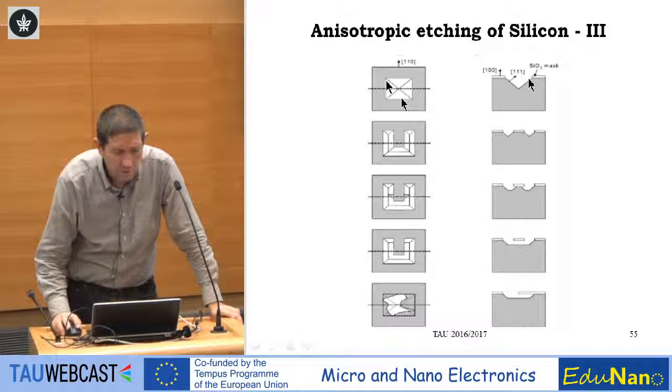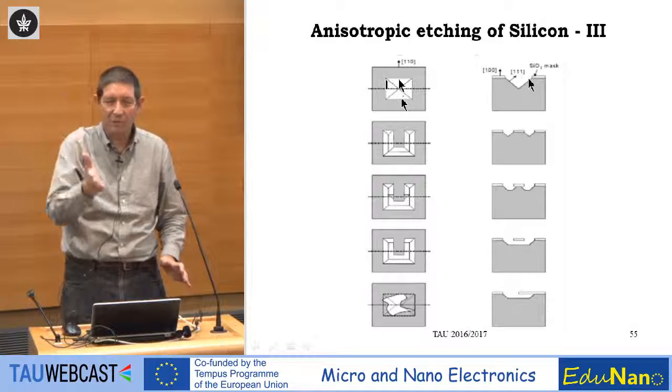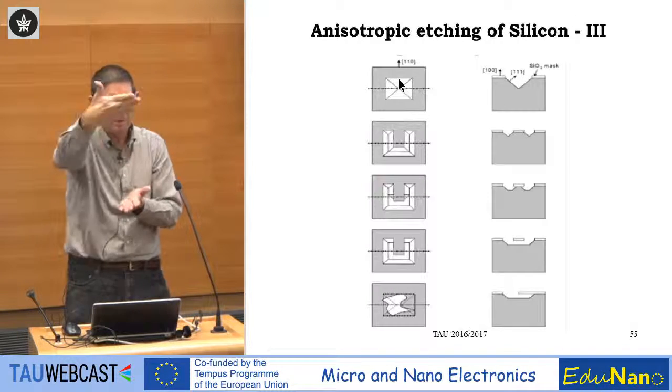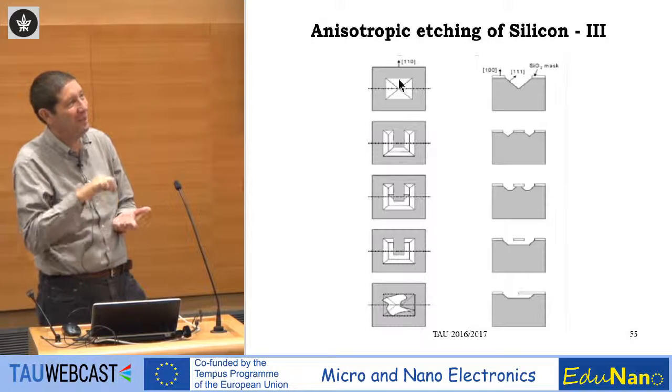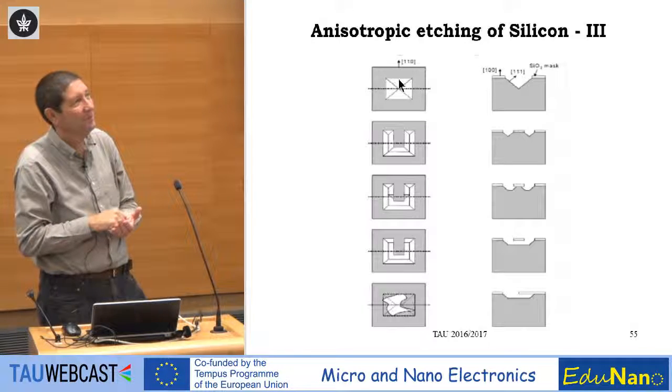What are the sides? What happens? This plane here is in 54 degrees. This is in 54 degrees. So you can calculate. You can use some simple geometry to calculate the depth of the pit.